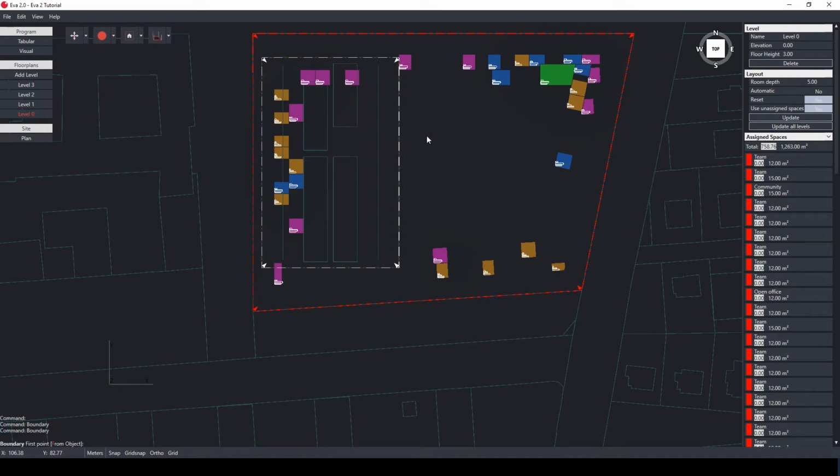We use the same procedure for transforming the inner lines to boundary line for inner courtyards. Without the existing polyline, we would immediately sketch the boundary line. Anti-clockwise for the outer outline, arrows point inwards, and clockwise for an inner courtyard, arrows point outwards.